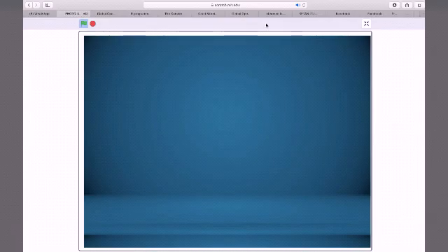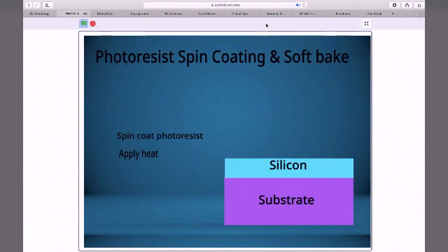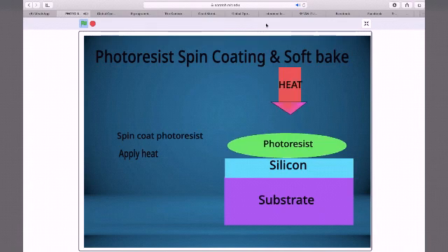The wafer is covered with photoresist by spin coating. Photoresist is dispensed onto the wafer and the wafer is spun rapidly to produce a uniform thick layer. The spin coating typically runs at 1200 to 4800 rpm for 30 to 60 seconds and produces a layer between 0.5 and 2.5 micrometers thick. Run-off of the extra photoresist is removed in a process called edge bead removal. To produce a flat layer of resist, the photoresist coated wafer is pre-baked to dry off excess photoresist solvent.